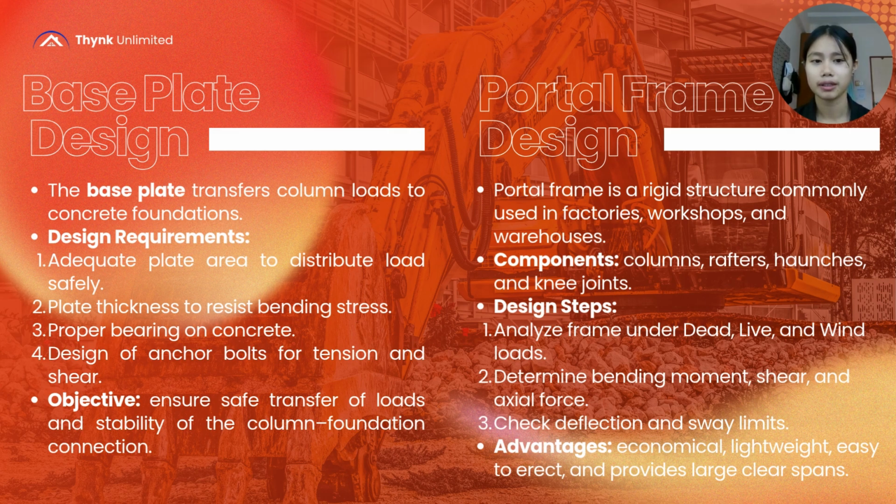Okay, in this slide, we have two designs. First is base plate design. The base plate transfers column load to concrete foundations. Design requirements: first is adequate plate area to distribute load safely.